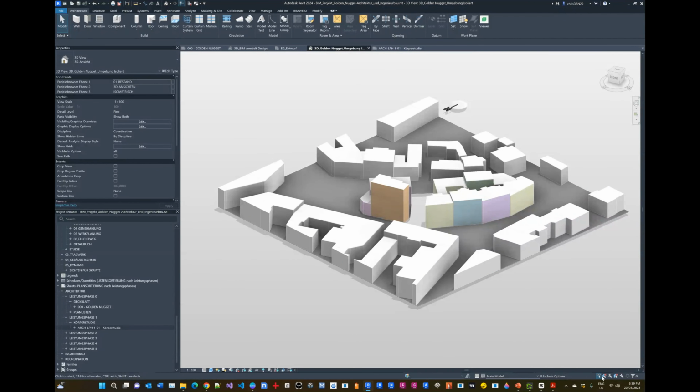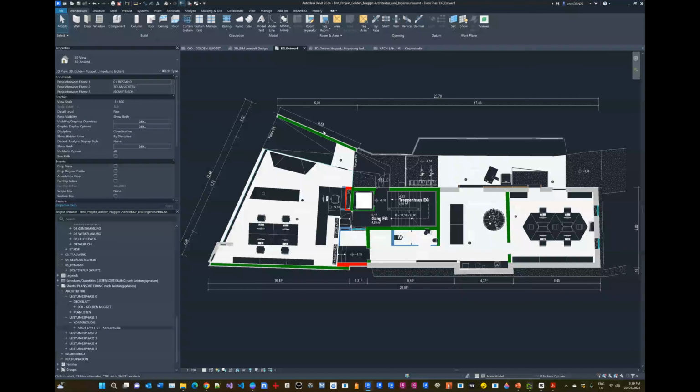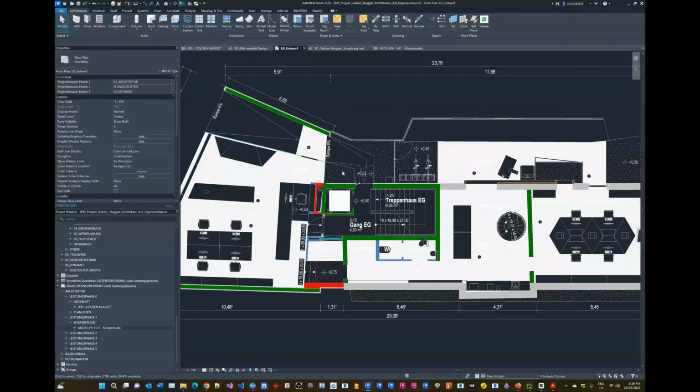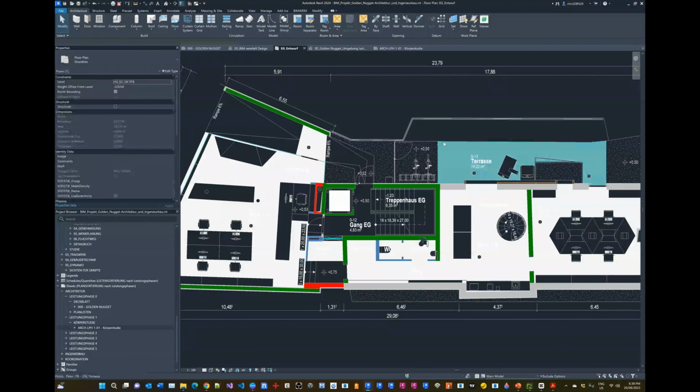At the bottom right here, we've got a toolbar where we can select different ways of behavior for when selecting elements. Now, often in the Revit environment, we've got components such as floors and walls and section views and so forth. You want to toggle between whether to select elements by face or not. If I switch this off, which is the default, you won't select elements by face, which means that when I move my cursor in plan view and I want to select the floor, I might not be able to select it unless I select the edge of that floor.